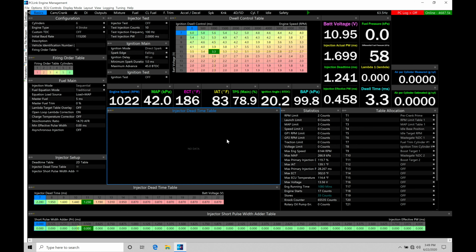One, we need to make sure we program our output so it turns on the cam switch at the proper time. And then two, making sure we have our fuel and spark timing accounted for so the engine is going to run properly and produce power when we're in our high cam operation.